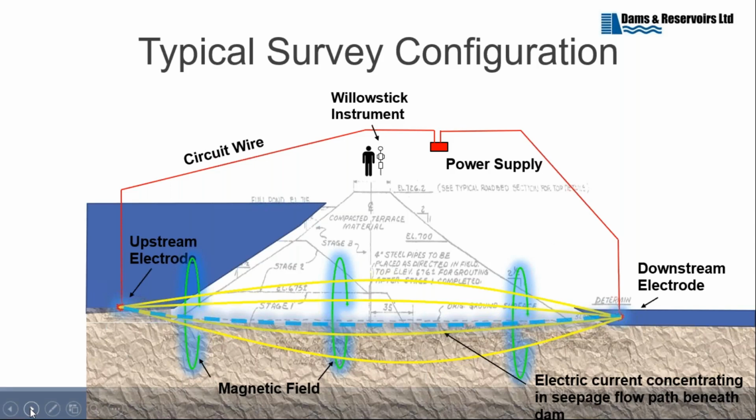And so in very simple terms, if we can trace changes in that magnetic field across that area, then we're actually finding the route of individual leakage paths. And then there's a clever algorithm that works out not only the location in plan, but also in depth. So we can actually plot individual leakage paths or seepage paths or flows of water, both in plan and elevation. And when you're faced with a problem, whether it's in a dam or any other sort of engineering structure, being able to locate a flow of water very precisely at considerable depths is a very useful thing to be able to do.